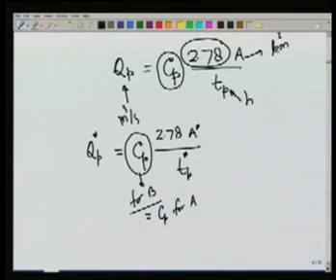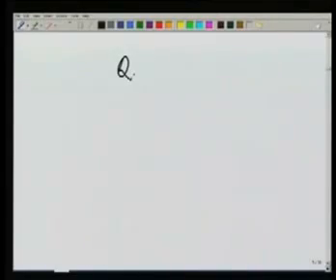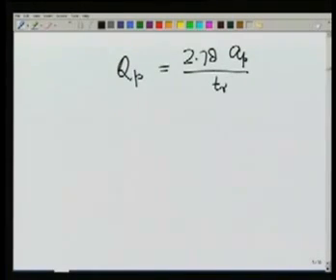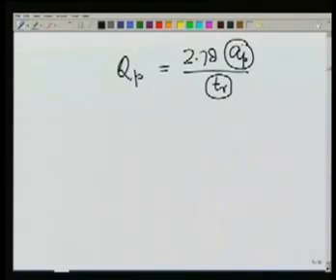Now this coefficient Cp can also be written as, if we look at discharge, the peak discharge, due to a rainfall of duration TR, which just says that intensity should be 1 over TR because we are talking about unit hydrograph, and Ap is the area which is contributing to the peak flow.